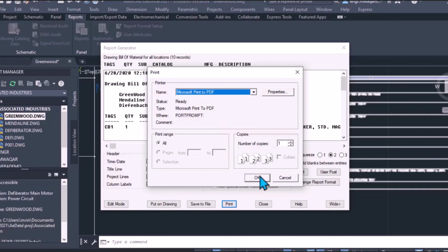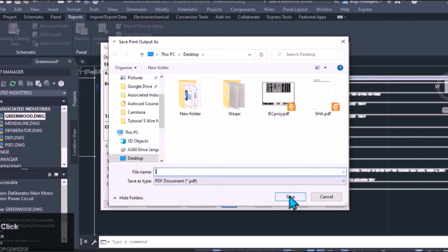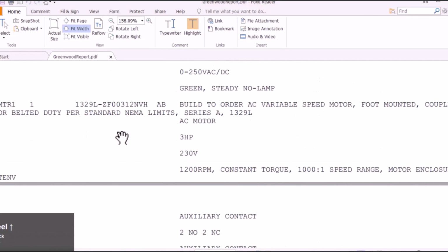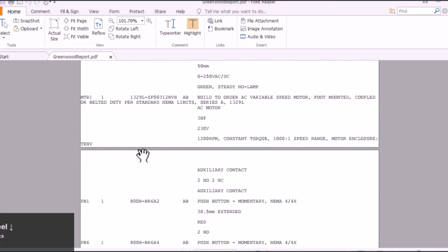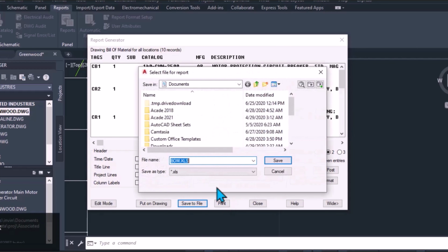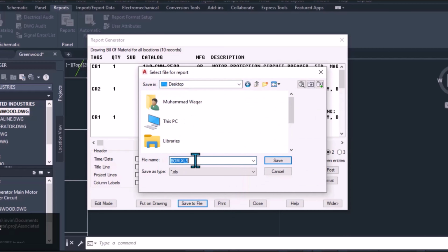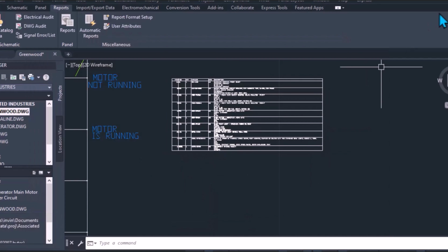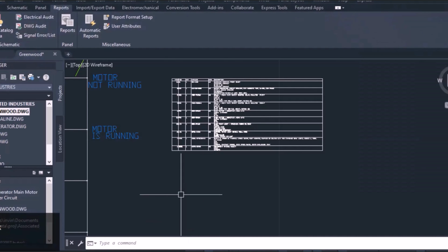You'd think so. But it needs the exact catalog specification, because in engineering, precision is non-negotiable. Right. If your visual symbol lacks underlying catalog data or an item number, the software intentionally ignores it when building the BOM because it literally has no idea what you want it to buy. It's like drawing a door on an architectural blueprint but forgetting to tell the builder what kind of door to buy. You're going to end up with a literal hole in the wall on moving day. That's a great way to look at it. The software doesn't just see a missing part, it sees a hole in reality.